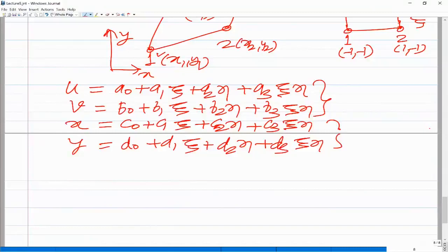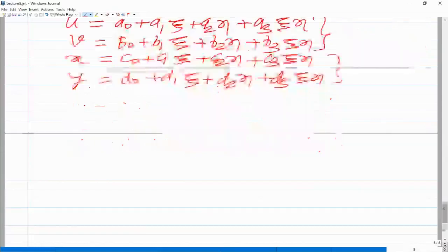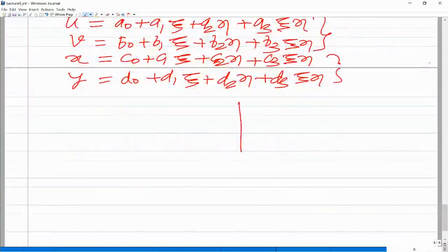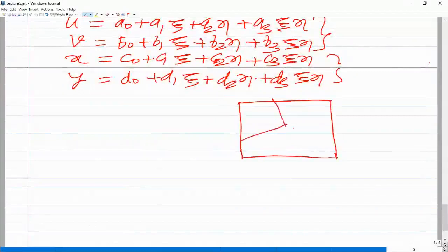I will, of course, be discussing how we get to the development of the element level governing equation from here. But for the time being, let me again talk of the compatibility condition, whether this element is compatible or not. So in the physical domain, let us say we have a domain and we discretize that into arbitrary quadrilaterals. So when we discretize this into arbitrary quadrilaterals, we have, let us say, quadrilateral elements like this. So this is the discretization.